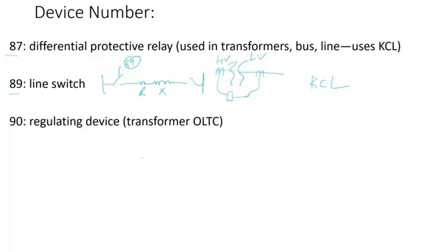For instance, if the nominal voltage is 12 kV line to line, and somehow the load was increasing and voltage dropped to 11.75 kV, and this is just a hypothetical example, the load tap changer would be asked to increase voltage by adding turns. So this device would be set to do that. You would give it some set points.